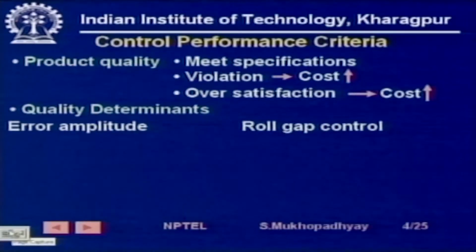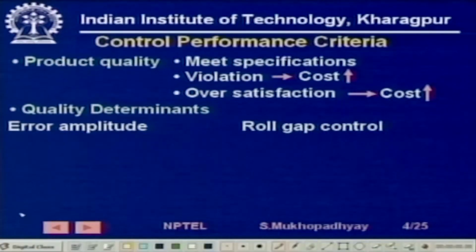If we have a rolling process, in a rolling process there are two rolls, and some plate comes in with some thickness, and when it goes out it has a lower thickness. So, there is a dimension reduction through the rolling. That is the job of the rolling process.